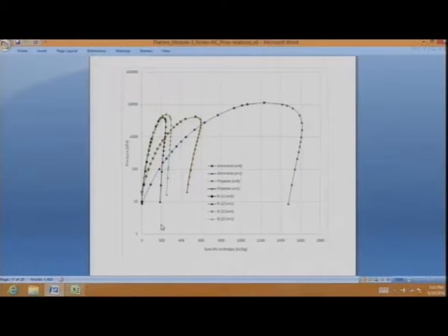But if those things are also okay, then what it means is that you can take the existing refrigerator or the existing air conditioner, throw out R12 and put in your new refrigerant, and your fridge and AC is good enough to keep working on. And that's what initially was done. But as time goes on, we came from R12 to 22. Now 22 has to be banned and removed.